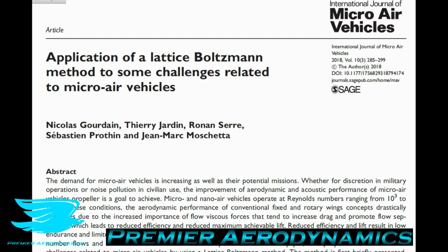However, there are some disadvantages to using Navier-Stokes for CFD, and we're seeing them now. So one of the major disadvantages is that it doesn't scale very well. And that means that when we try to solve very complex or very computationally expensive flows, our main go-to method is just using more cores, more CPU, more computational power. However, there's a limit to that, because let's say you have one core or one thread or whatever you want to call it, I usually say core. If you're not used to that terminology, let's just think of it as a CPU.